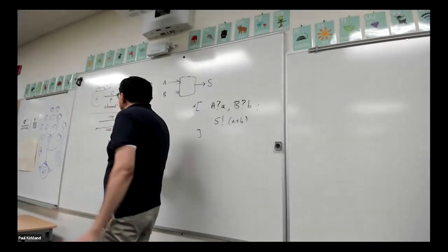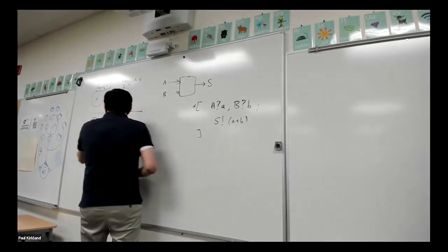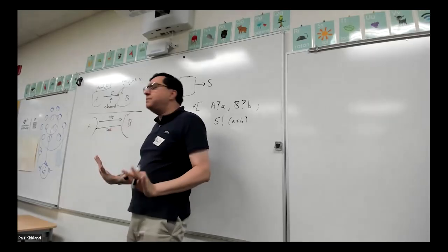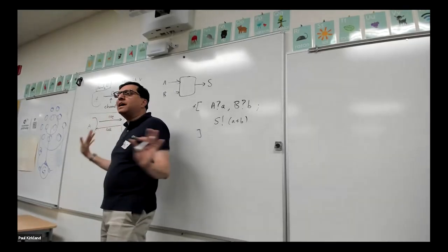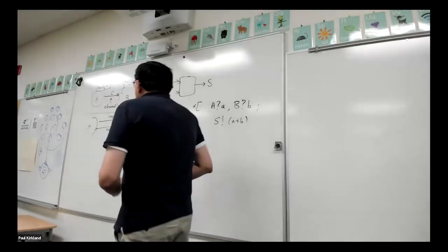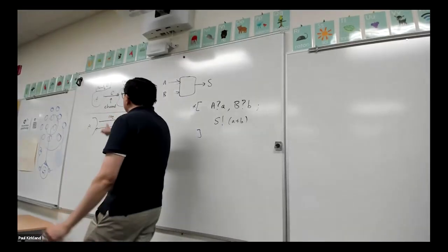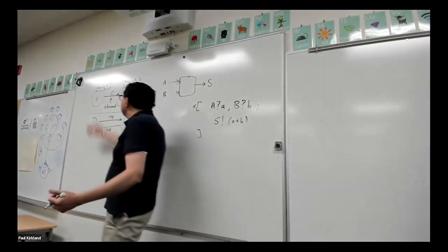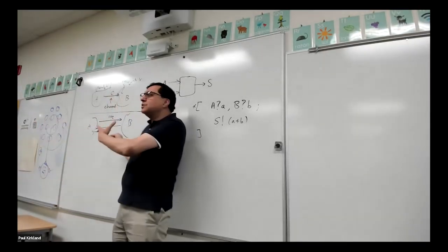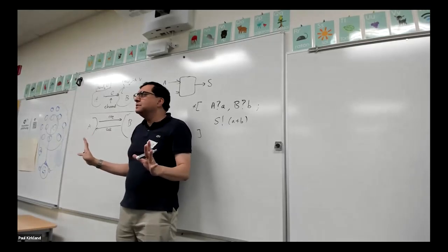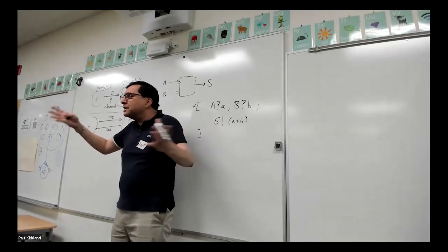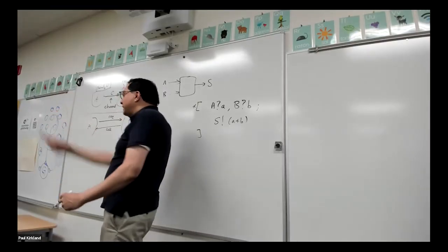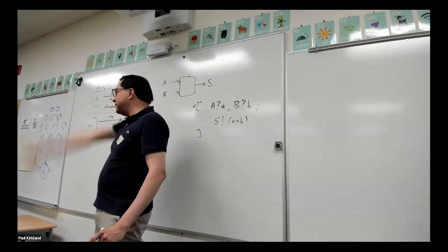So you do a handshake. Here is A, and here is B. Since send and receive with no data are symmetric, I could also flip who's the request and who's the ACK. That's a choice, but let's just pick something concrete. The wire labeled request is the side that initiates the communication. You all know a handshake protocol, RS-232 for example, the VME bus, millions of them. Exactly: request, ACK, reset.